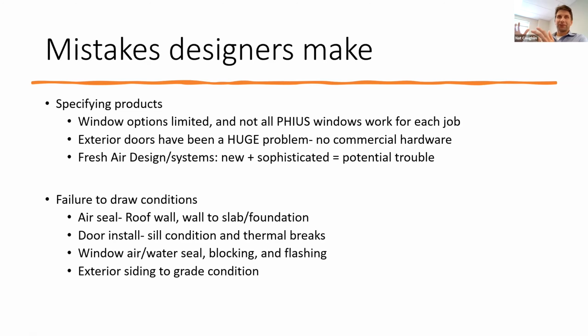For years, architects have been just living with kind of a thermal break there because they bring the concrete up a little bit above grade so that it meets code, and then your Hardie plank or whatever starts above that. Now you bring up insulation and you have to find a way to cover that insulation that's on the outside of the foundation. It's a little different, at least in our experience, from what we've done before.